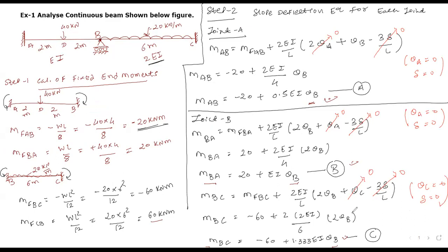Please confirm me. For an example, if we again move to this plan, for this joint, the moment coming from this member, this member, and this member, having some equilibrium conditions, is nothing but the algebraic summation of all forces will be 0. Is it clear or not? This does not mean that the joint is not resisting a moment. It will carry a moment, but in equilibrium conditions. Is it clear or not? Please confirm me. Yes, sir. Understand, sir. Okay, fine.